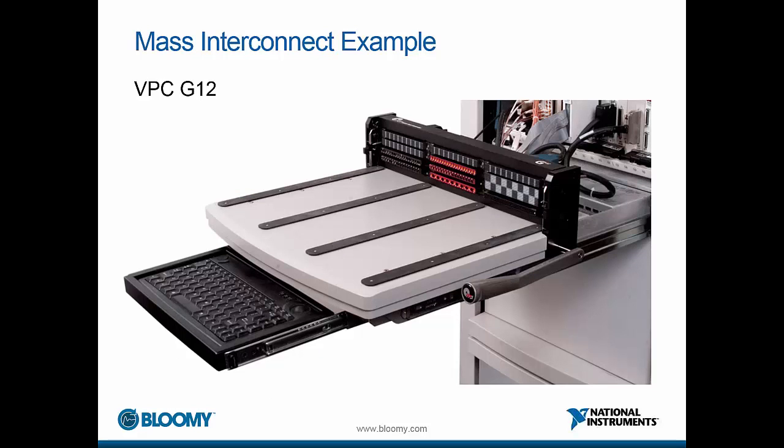Here we'll take a look at one example of a mass interconnect receiver, the Virginia Panel G12. This particular mass interconnect provides space for up to 12 modules, laid out in 4 rows and 3 columns. Each module is essentially a mounted connector, and there are many different configurations available, such as high-density 192-pin signal modules, lower-density high-power modules up to 65 amps, and coax and pneumatic modules. In addition, many of these modules have PCB-based interfaces to allow them to easily plug and play with standard cabling to common instrumentation.